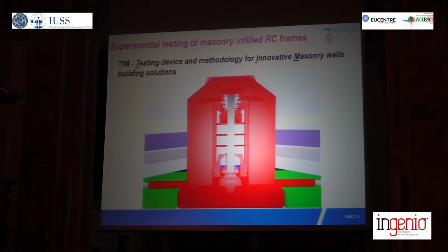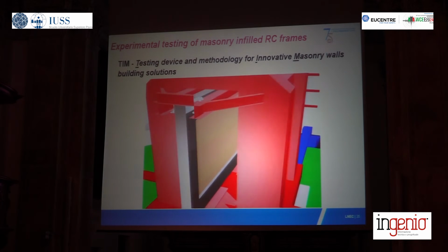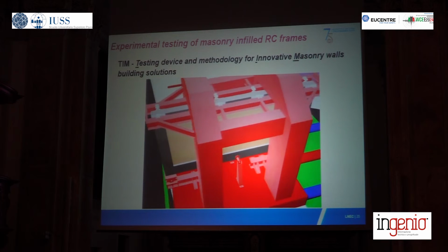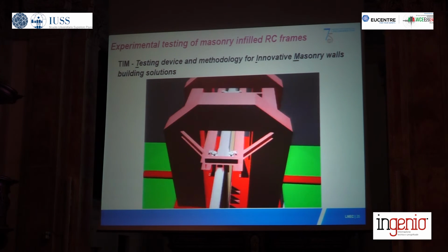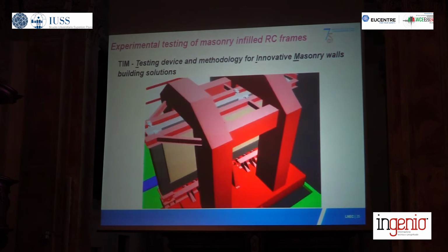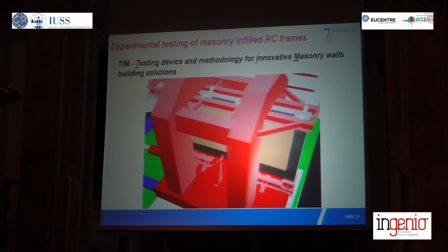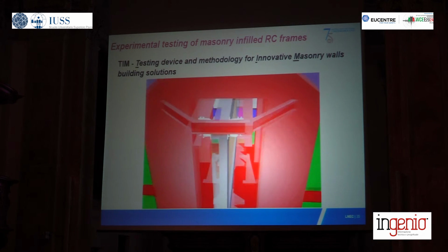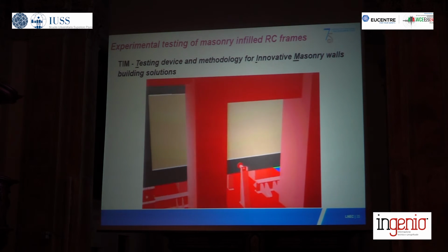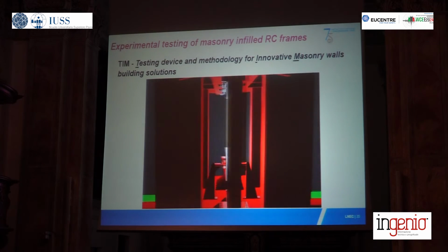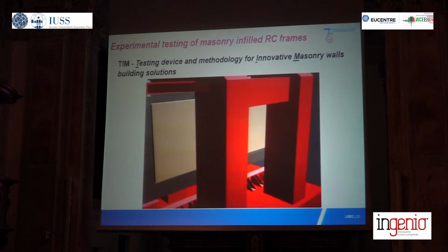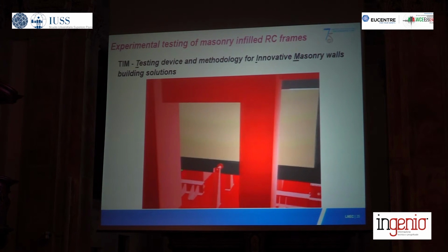So just taking a look at the device, a small animation to look at different details. We have rollers at the top beam to allow the shake table and this large steel structure to move along the longitudinal direction of the beam, while still being able to impose the out-of-plane drift.